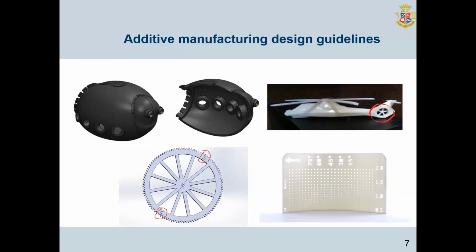When designing parts for additive manufacturing, attention must be paid to the minimum dimensions of holes and other elements, for example, text and small decorations. In this regard, recommendations are individual for each material and additive manufacturing equipment. It should also be taken into account that after cooling, the material can shrink, and at the same time, the geometry of the object changes.